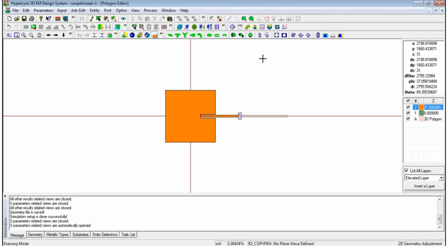What we can expect from optimization. Okay, this is all about optimization in IE3D. It will depend upon the structure. The more accurately we can optimize it in the IE3D library, because the IE3D library is more of a parameterized design. So I have better control over the parameters for optimization, and I can define multiple variables for optimization.